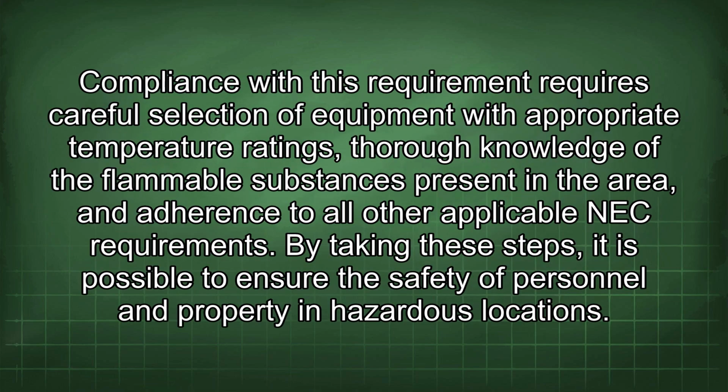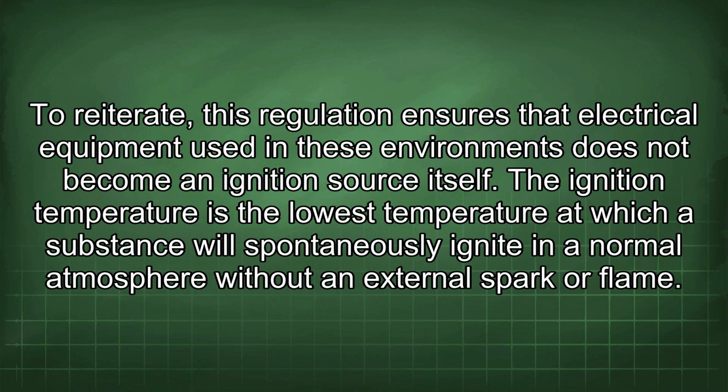Compliance with this requirement requires careful selection of equipment with appropriate temperature ratings, thorough knowledge of the flammable substances present in the area, and adherence to all other applicable NEC requirements. By taking these steps, it is possible to ensure the safety of personnel and property in hazardous locations. To reiterate, this regulation ensures that electrical equipment used in these environments does not become an ignition source itself.